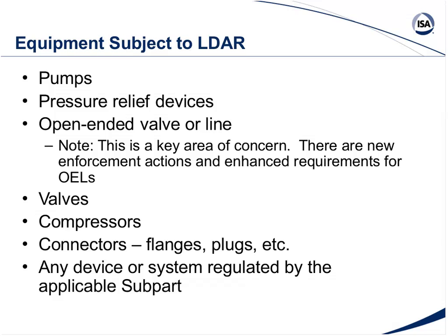But when we terminate the end of that pipe so that we don't have a leak, it's not really an open end anymore. However, under the rules, we now have to go out and inspect those, quote, open ends. Because anytime I have a flange or a plug or my valves didn't quite hold, my second valve didn't quite hold, and I'm actually seeing emissions at that termination, that's now considered an open-ended line.